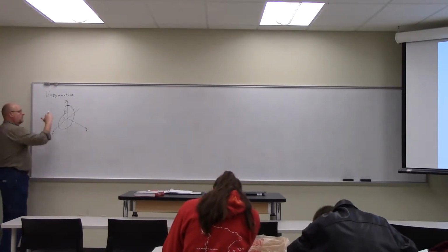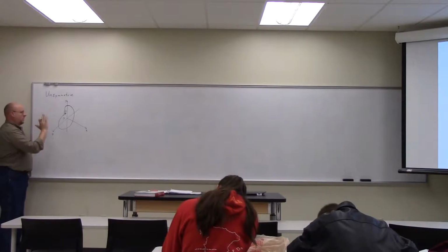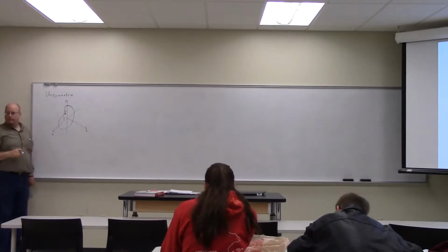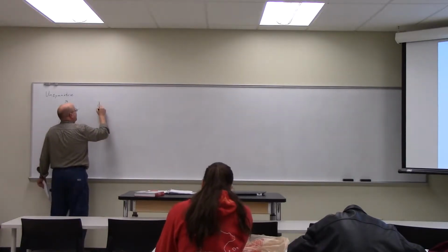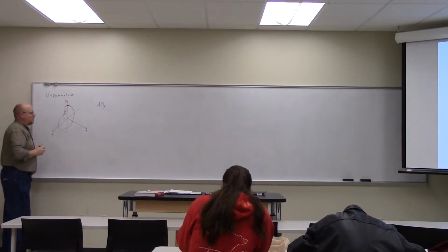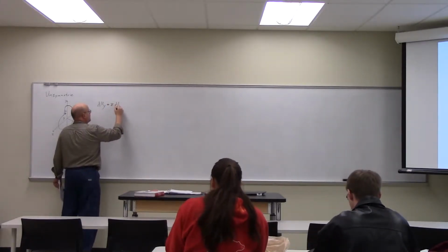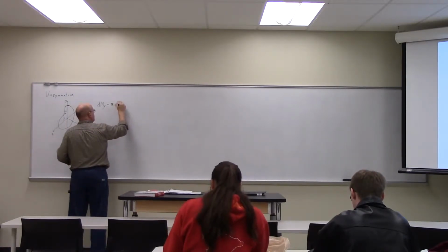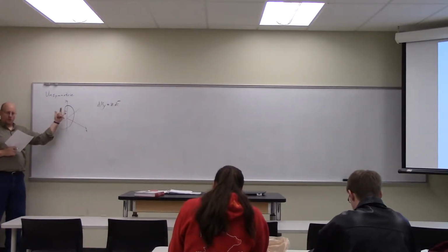But we're still applying a moment in the z direction, right? So you note the moment out there is still a pure z moment. We're trying to bend this bar upward, but now the bar is asymmetric. Okay. So the moment about the y-axis contributed by this little element is going to equal z times dF. Z is the distance away from the y-axis, so it's going to create a moment about the y-axis.